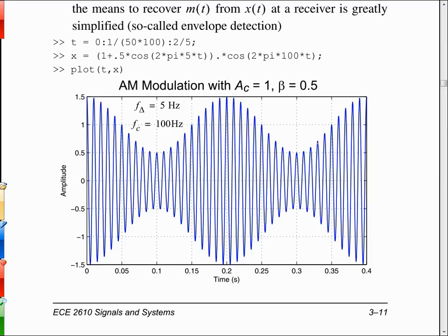In a typical AM broadcast medium, they can broadcast with frequencies in the message that go up to about 5 kilohertz. And therein lies the problem. That's why AM doesn't sound very good, because they're only allowed to broadcast spectrally message frequencies up to 5 kilohertz, whereas high-fidelity audio we think of as going up to 20 kilohertz, with our hearing, tapering off around 16 kilohertz in that neighborhood, depending upon our age and abuse to our ears.